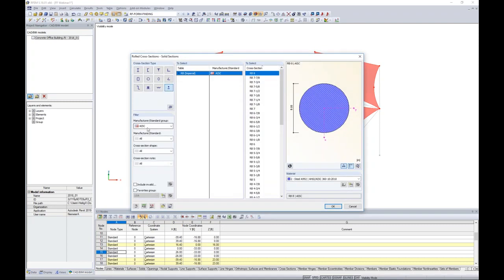In particular, today I'm going to use the solid sections. This just has some pre-populated diameters. They're basically just round bars populated from the AISC with set diameters, but you can always create your own with a parametric section. We'll choose a 1/2 inch diameter cable. The material is also set within this same dialog box.